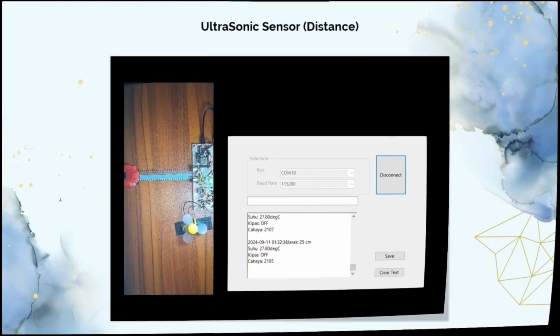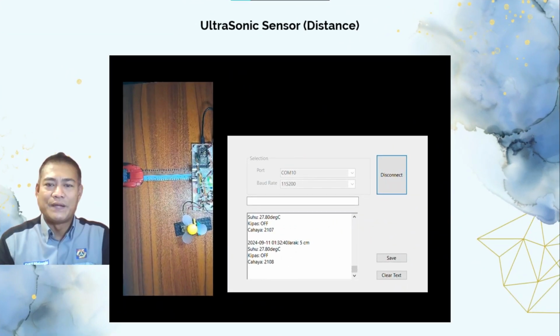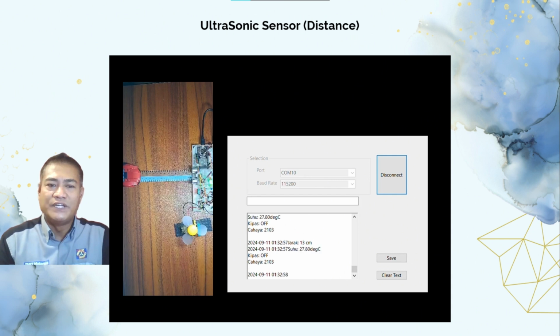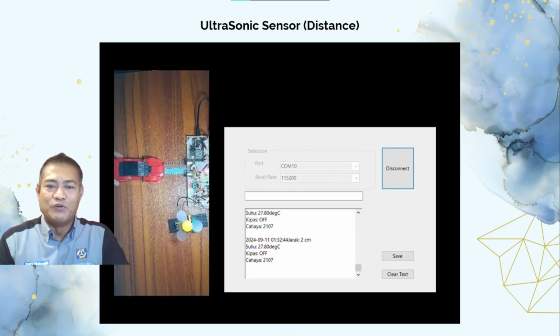time. In these demonstrations, the Arduino program is designed to activate a buzzer when an object is detected within range 12 centimeters or closer. Using an ultrasonic sensor, the system continuously monitors the distance of nearby objects. When something comes within the set range, the buzzer automatically switches on to give an alert. Once the object moves beyond 12 centimeters, the buzzer stops.